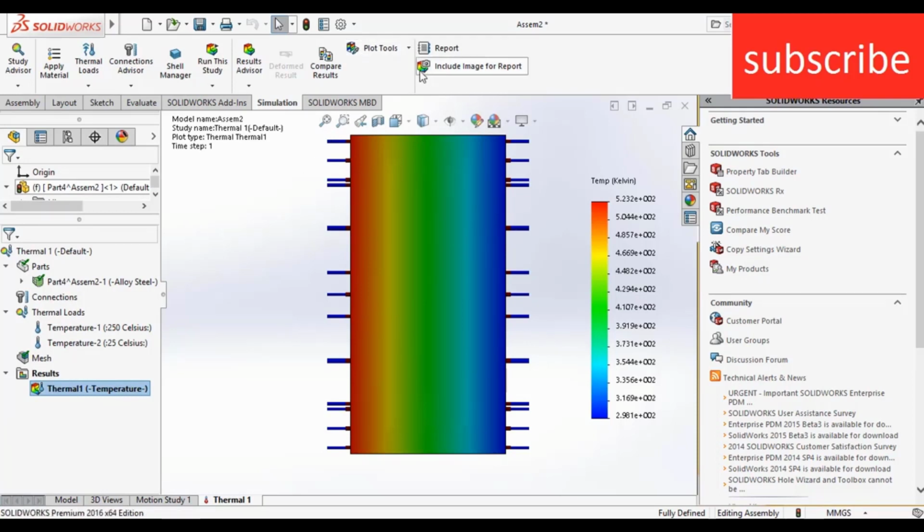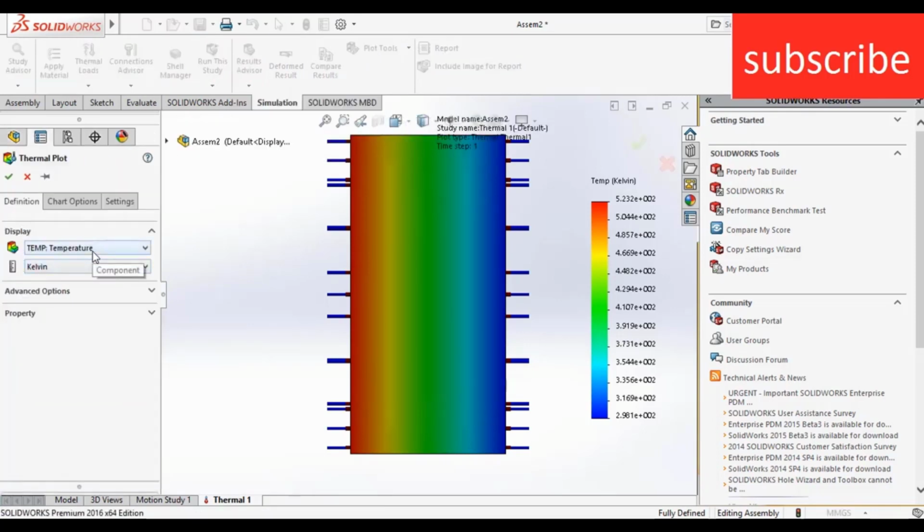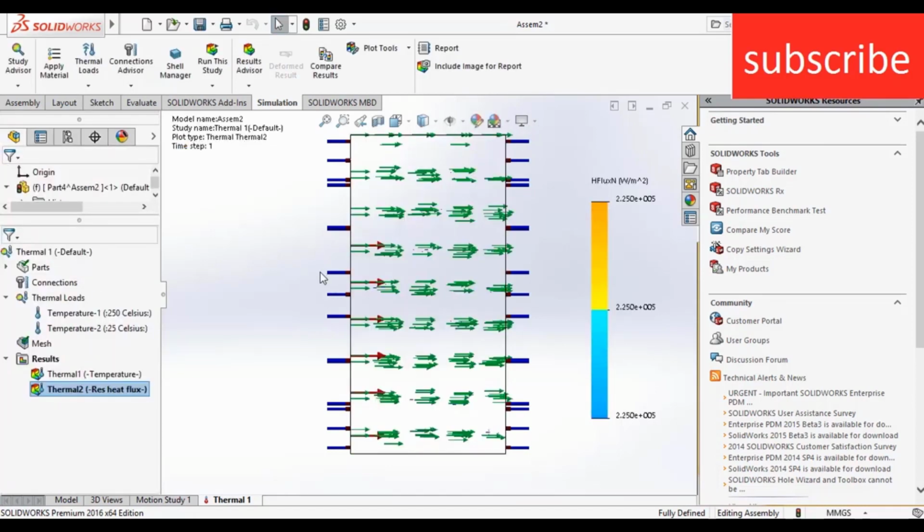To calculate heat flux, go to result advisory, click on new plots, click on thermal. After that, on display, click on it, select resultant heat flux. Remember, it doesn't matter what the heat flow in X, Y or Z is. The main thing I am focused on is the resultant. That is the reason I am clicking on resultant heat flux. Make sure the units are in watt per meter square. Click on show vector plot to better show how the heat flows.